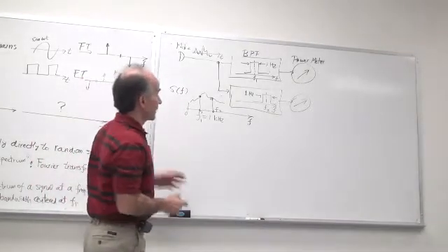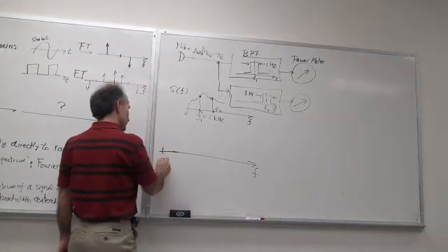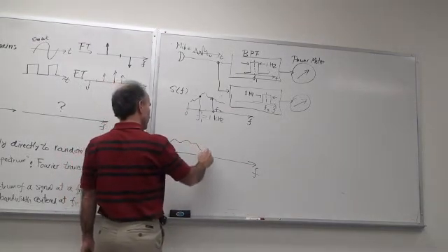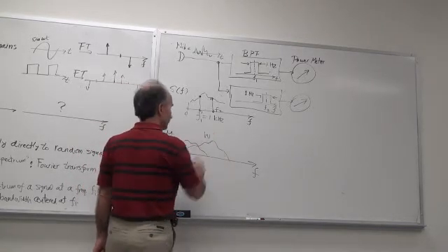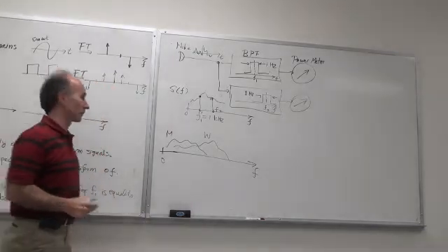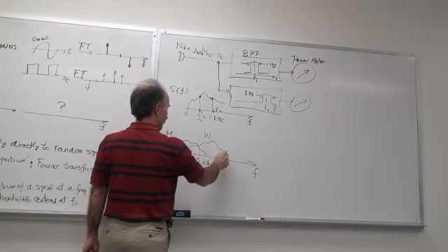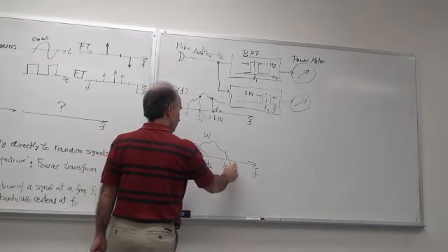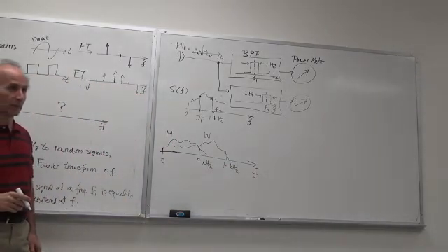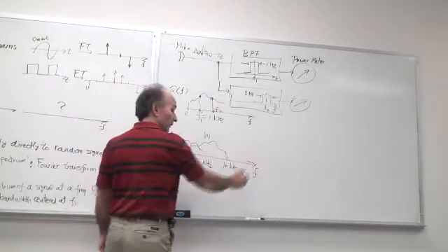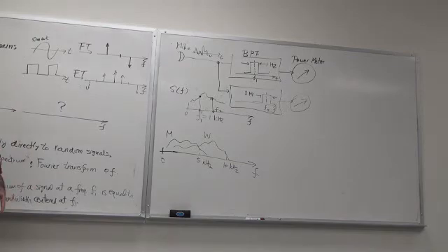So if we perform this test for a woman's voice versus a man's voice, this is what we should observe, right? So a man's voice has lower frequency components. That's a man's voice. And a woman's voice has high frequency components. So that's a woman's voice. Okay, so for example, a man's voice may cut off around 5 kilohertz, whereas a woman's voice may cut off around 10 kilohertz. And by cut off, I mean it becomes negligible past that point. All right. A children's voice might actually extend all the way to 20 kilohertz. All right, so that's what we call the spectrum of a signal.